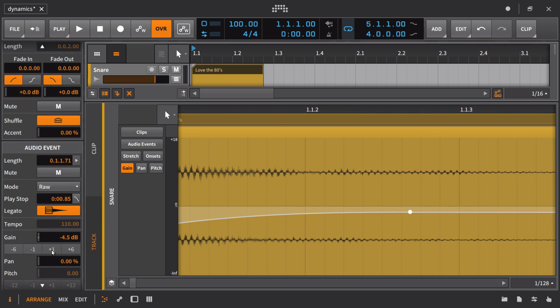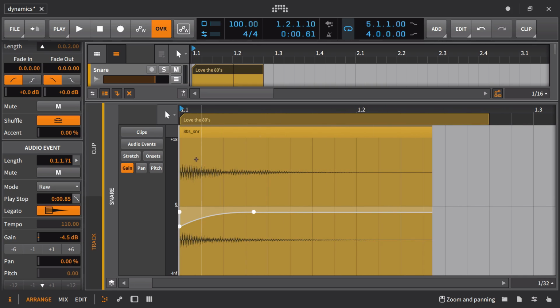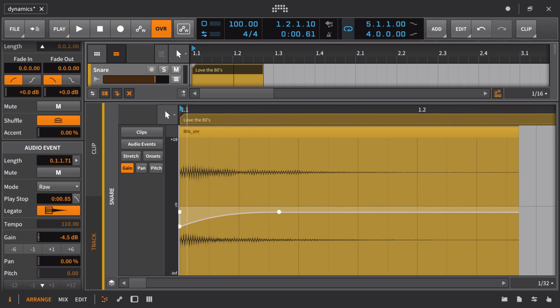1, 2, 3, 4. And perceptually, it should actually now sound louder because we've reduced the difference from the peak to the rest of the signal. And also another sort of perceptual thing with our hearing is that super fast peaks, even if there's a huge difference, you don't really hear it as such. So in a lot of cases, it actually makes sense to go in and reduce the peak energy, mainly just because it's taking up a bunch of headroom for no reason. So that's really the basics of downward compression.